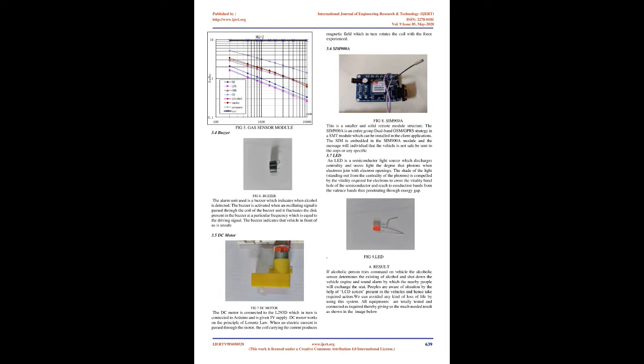driving. The MQ3 sensor detects the presence of alcohol in the surroundings. The sensor provides output on the basis of the concentration of the alcohol. If the alcohol concentration is higher, the conductivity of the MQ3 sensor increases, which in turn gives the reading to Arduino. If the reading is greater than the threshold level, Arduino will stop the DC motor.